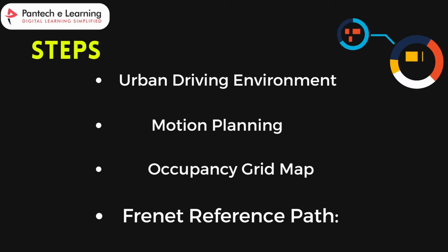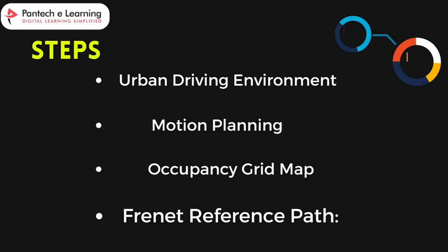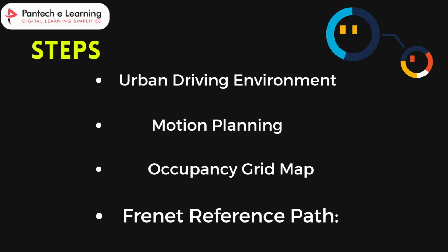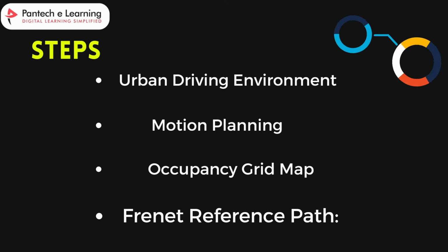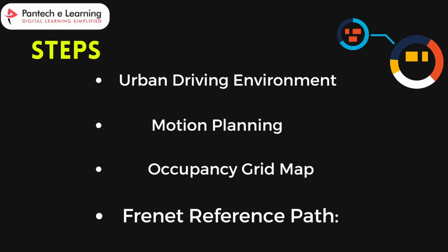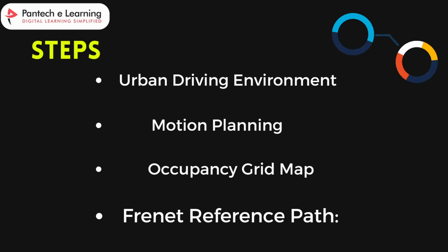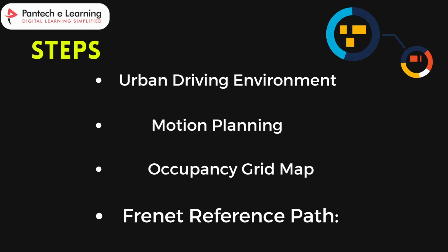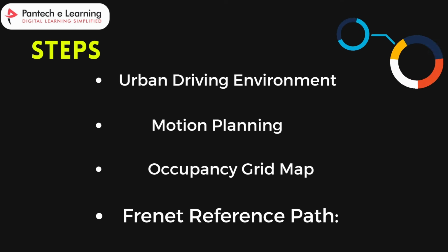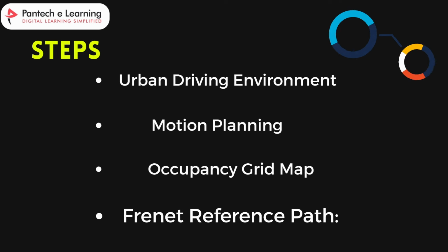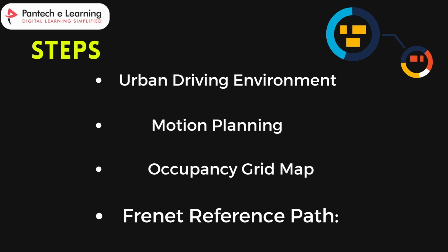Additionally, dynamic replanning also involves this step: continuously updating the vehicle's trajectory based on the evolving environment. This may include updating the occupancy grid map, re-estimating the vehicle's position and orientation, and generating new trajectories or new waypoints to avoid any obstacles and reach the goal. That is why we use dynamic replanning.